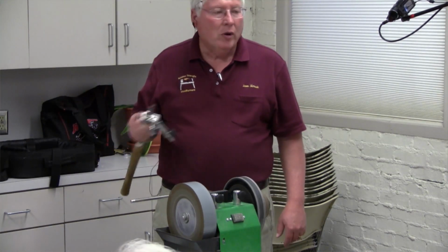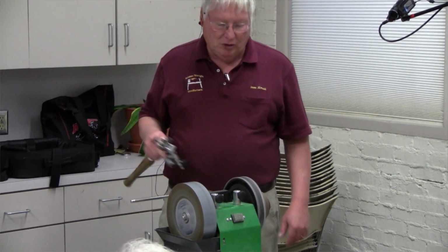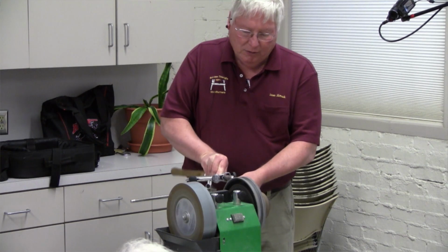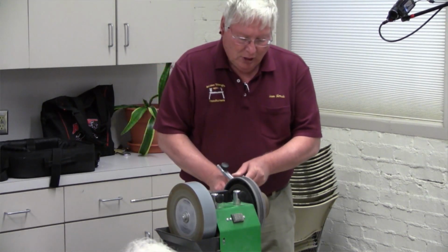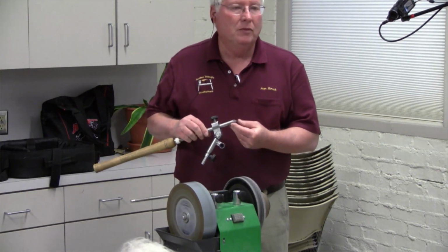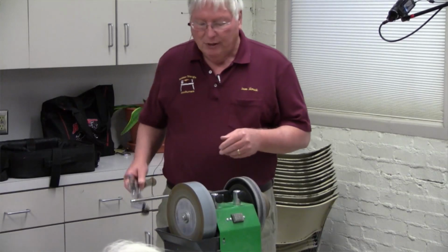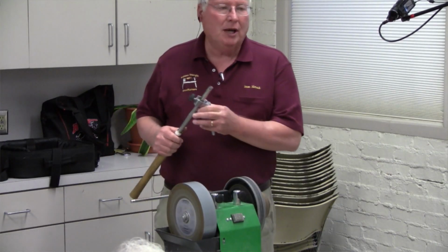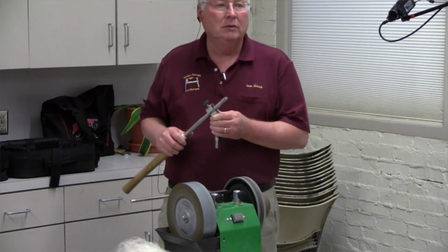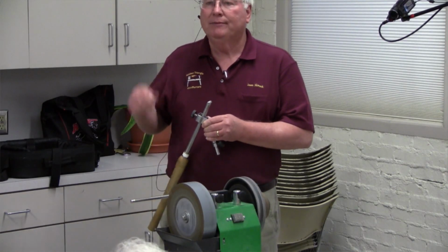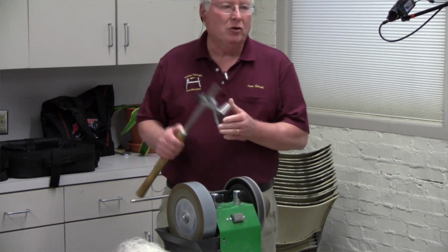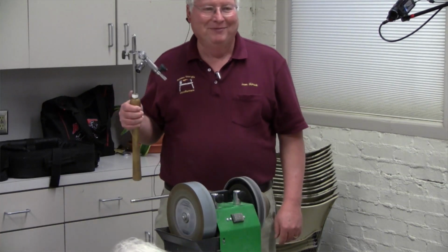So very quickly you can go back and put a very sharp edge on the tool, and then with the leather stropping wheel you can polish the edge, and you can take care of the burr on the inside, and then you're ready to go with a nice sharp tool to start again. Again, much like the Wolverine, a lot of flexibility depending on what you want the profile of the tool to look like, and to be able to repeat it time and time again with a specific tool. And my memory is so good, that's why I put the tape on there with the numbers.